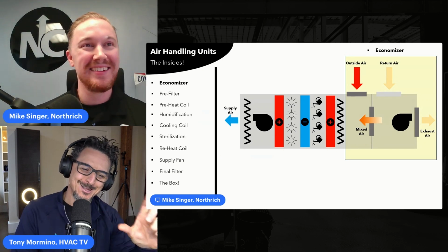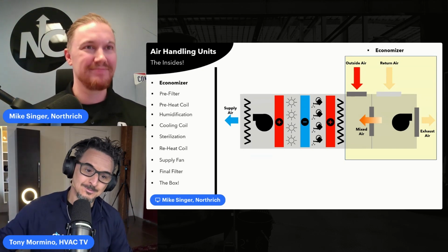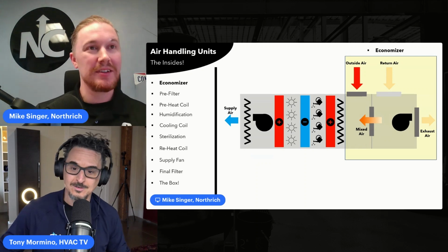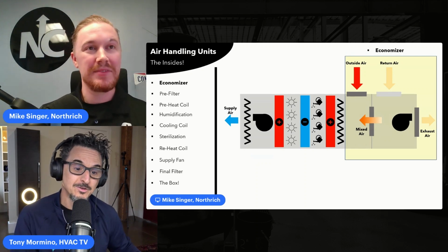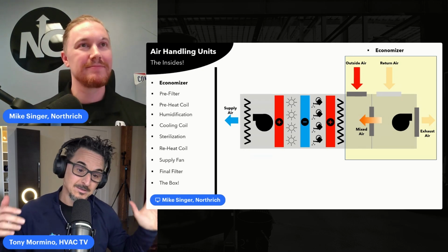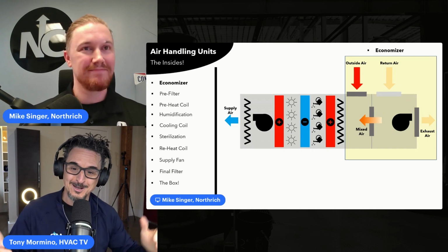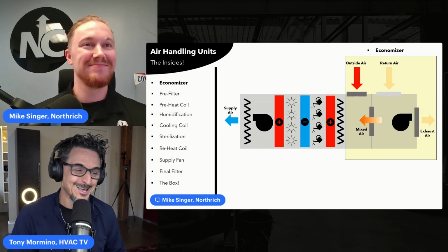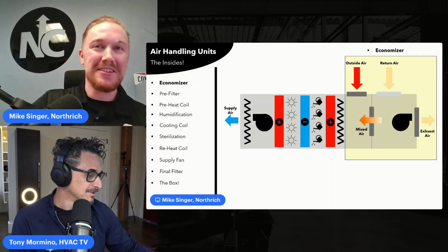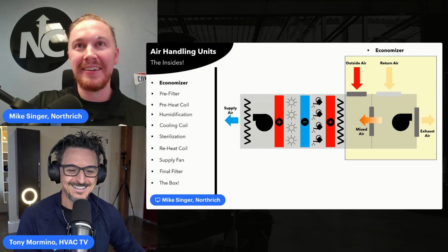And before you go on to that, the base rail, the higher the static pressure of the unit, the more room you need for a trap. If you've ever gone to a job site and seen a hole cut in the floor, it's because they didn't have enough room for the trap. It's a very unforgiving situation when you have a 40,000 CFM air handling unit sitting on a slab in a room and you need another inch. It's not easy to raise it up an inch once it's installed. Somebody winds up hitting concrete with a sledgehammer. You're right, Tony.